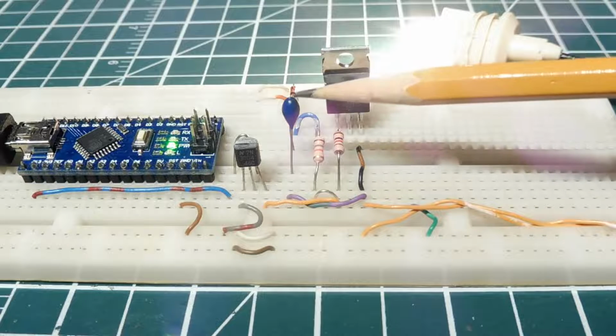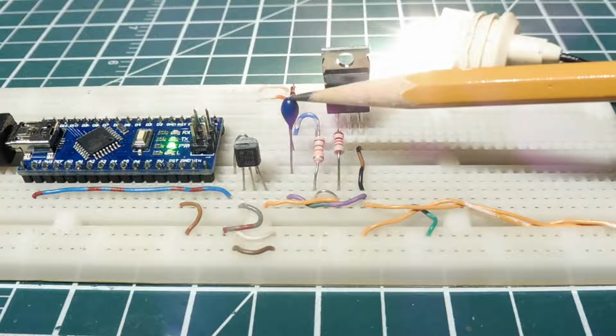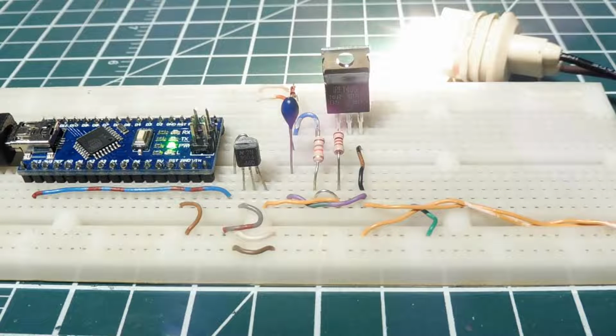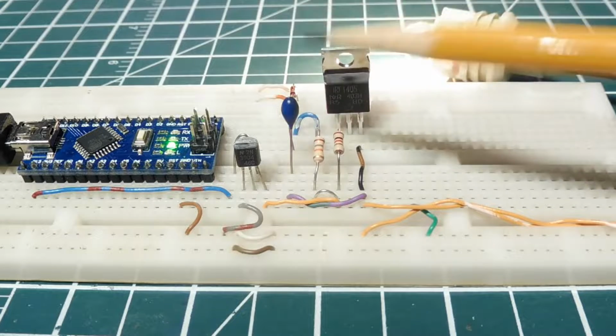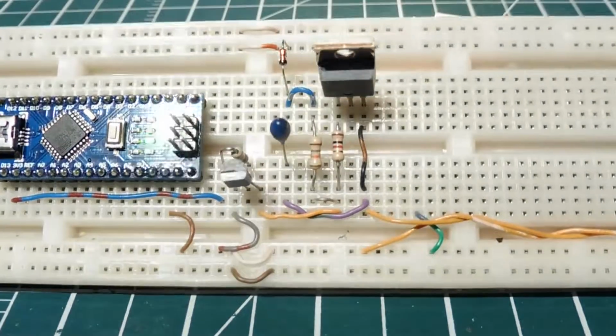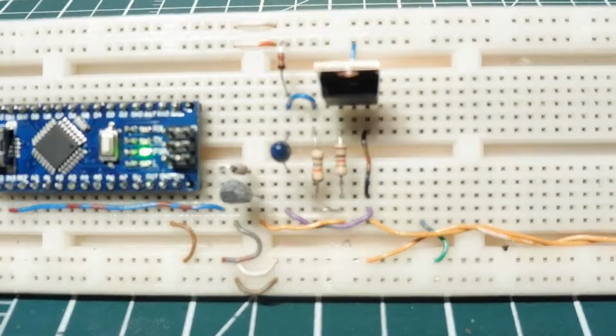Now after a certain period of time, this capacitor is going to drain off. It's going to leak out through the diode. You can see the diode over here. So eventually we'll lose our drive. This is an on-off type circuitry, like a hammer driver. If you say drive a solenoid, it's on, off. Every time the bulb goes off, it's going to recharge the capacitor. So this is more of an on-off circuit than a steady state on circuit. But it's a low parts count, and we'll have a look at the schematic to see how the circuitry works.